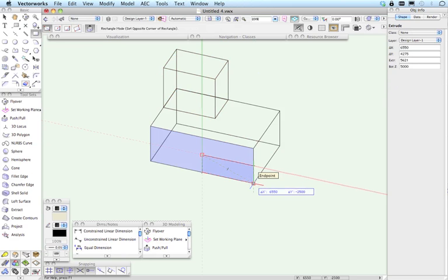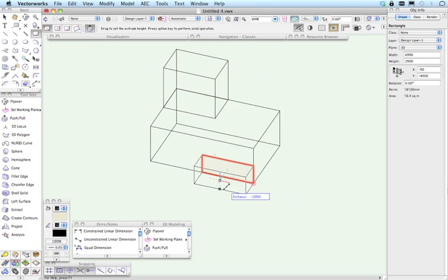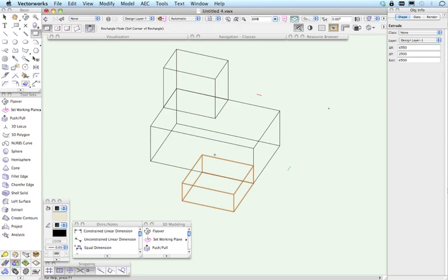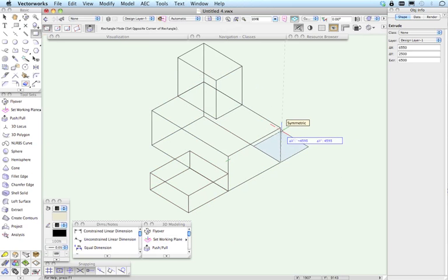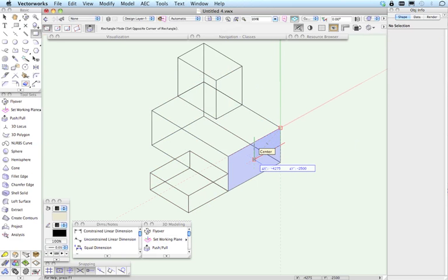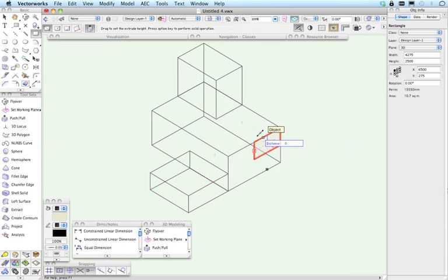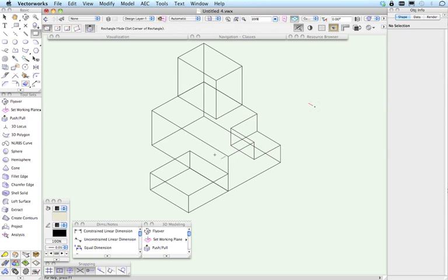Let's try that on this face. So let's say go from this corner down to here, and put the cursor back over the object I've drawn and click drag, and we can then use the push-pull mode. Now one additional feature which is very powerful is that if we do exactly the same thing, this time I'll just move this around a little bit. This time I'm going to take the rectangle tool and draw exactly the same way from, say, this corner here. Let's just get that automatic working plane happening first. And I'm going to draw it to the center here. Then I'm going to use the push-pull operation, and I'm going to push in here. Now at this point, before I do my second click to complete this operation, if I hold the optional Alt key down, it will subtract that shape from the shape that I drew it on.